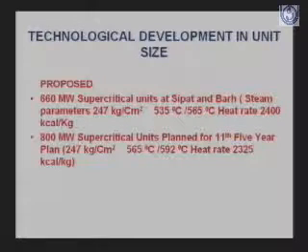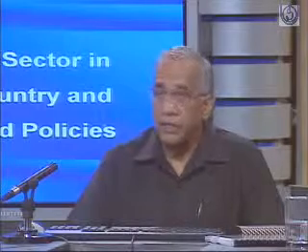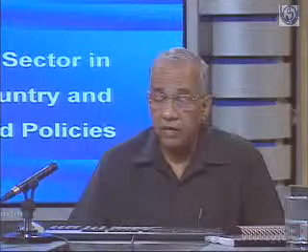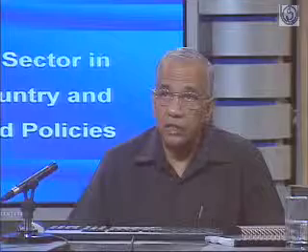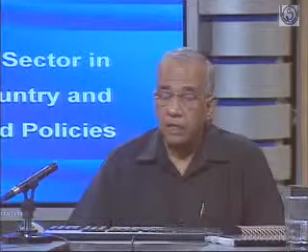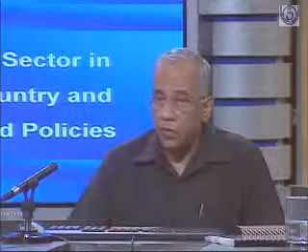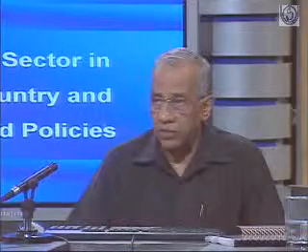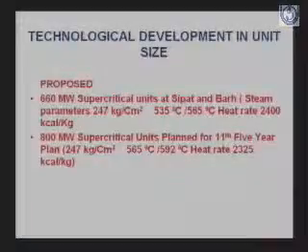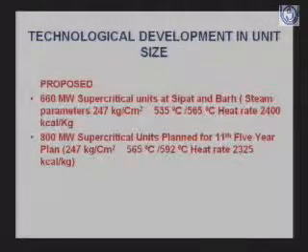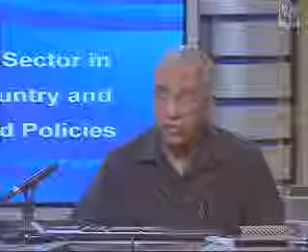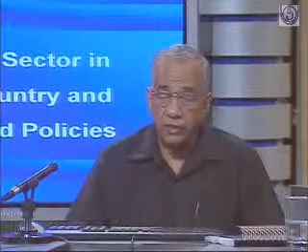Now someone can again ask why did you adopt a higher temperature of 565 on the reheat system, why not 565 in the main steam as well? The efficiency could have increased. Yes, theoretically speaking, the efficiency could increase if we have a higher temperature, but then you see the main steam pressure is high, the reheat pressure is low. So combined together, if the pressure is low, we can go for higher temperature to keep the stress values the same. If the pressure is high, we will have to keep the temperature low so that the stress values are the same as per the metallurgical considerations of that material.